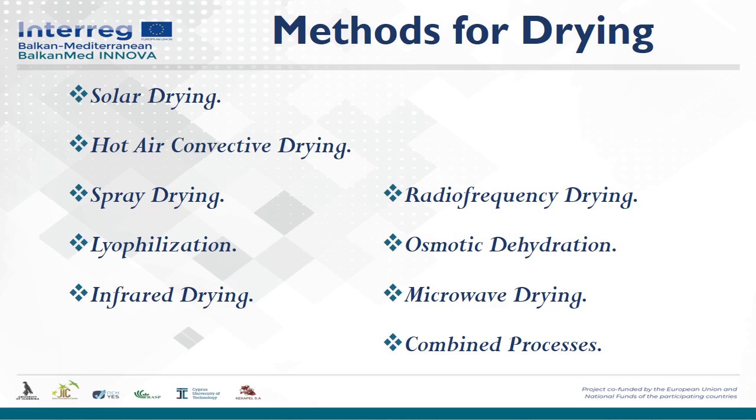Lyophilization is another method for drying, also called freeze drying or freeze dehydration. In this case, the water is first frozen and then sublimated under special conditions of pressure and temperature. Well, lyophilization is slower and with higher costs. Mostly in industry, this method is used for the dehydration of foods, for example, the dehydration of mushrooms or herbs and spices, fruit juices, etc.